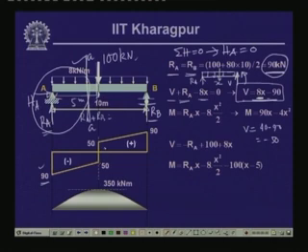Now, at this particular point, if I exaggerate the shear force diagram, precisely the concentrated load acts at this point, and we are evaluating the shear force a little left of this load. So, basically we have the ordinate over here as minus 50. Let us assume for the time being that we have this variation from here to here, which is linearly varying with respect to x.